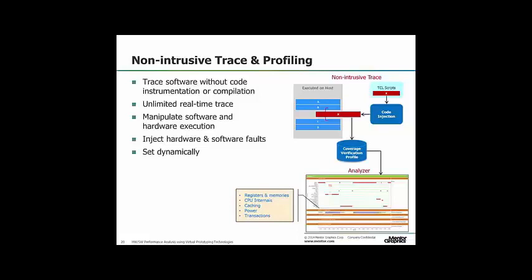We can also use this mechanism to inject extra code to impact the behavior or inject faults into the software. And because, again, this is non-intrusive, it's not impacting any of the data and the analysis results that we're collecting as we run the simulation. All of this is dynamic, so we can enable or disable tracing of particular functions at any point in time during the execution of the virtual platform.